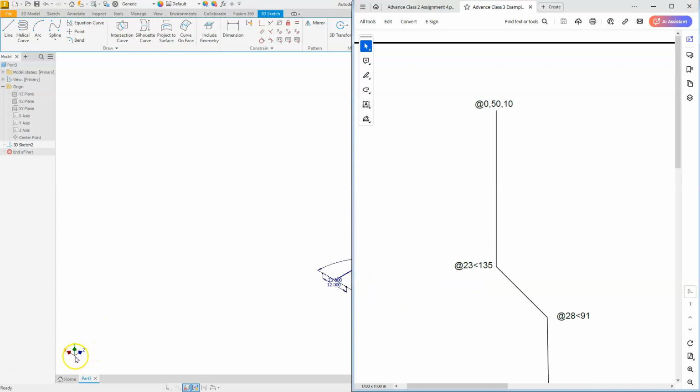So kind of looking at the drawing here, I'm looking at this UCS, and you see I wanted to go this direction, 50. So therefore, that's why my Z direction is 50. I wanted to go up in the Y direction. That's going to be my 10, and the 0 is my X. So it's really important that you take a look and understand what's happening here.